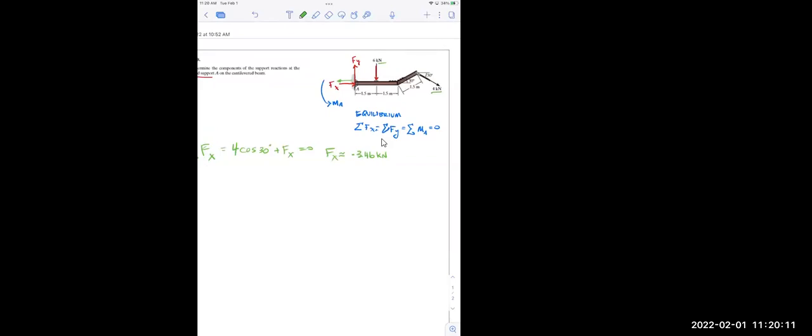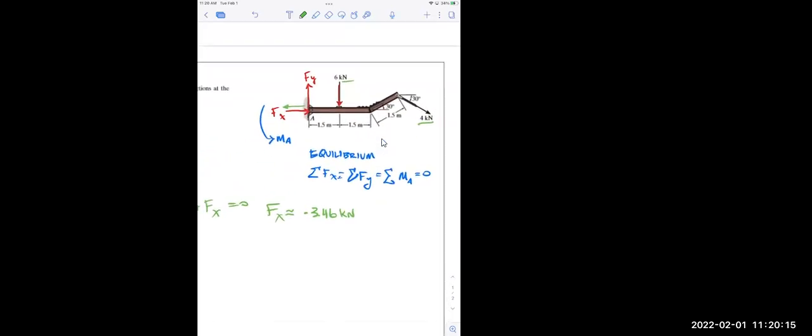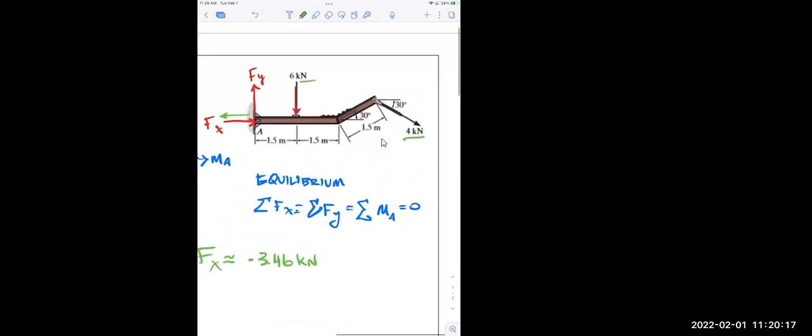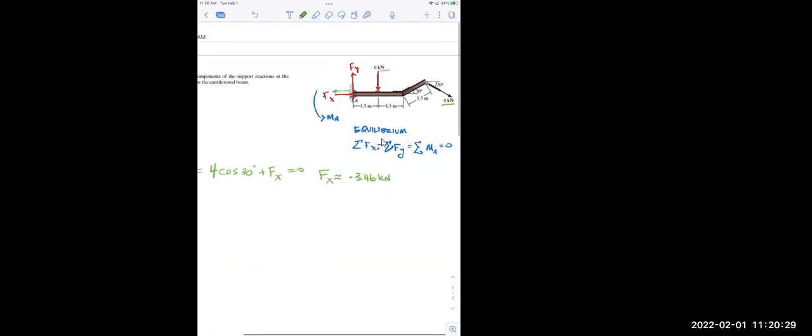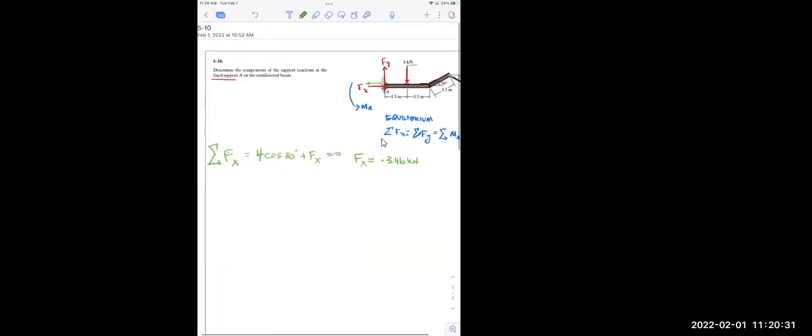That worked out okay. Can you tell that I got the force of Y kind of right by logic? Because isn't the 6 and the 4 both going down? So wouldn't the wall basically have to pull up in order to stop that? So, you know, that's good. At least the force of Y is going to come out the correct sign here. I can see that now. So what's happening with the force in Y? Well, I've got -6 kilonewtons going down. Don't have to modify that.